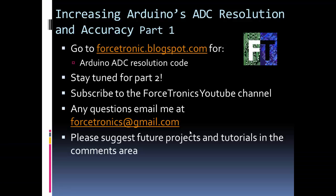I should mention, what if your voltage that you're trying to measure is much higher than the ADC reference? Well, you can use a simple resistor voltage divider to bring down the voltage to match your ADC reference. And I've talked about voltage dividers in other posts. What if your voltage is very, very small?